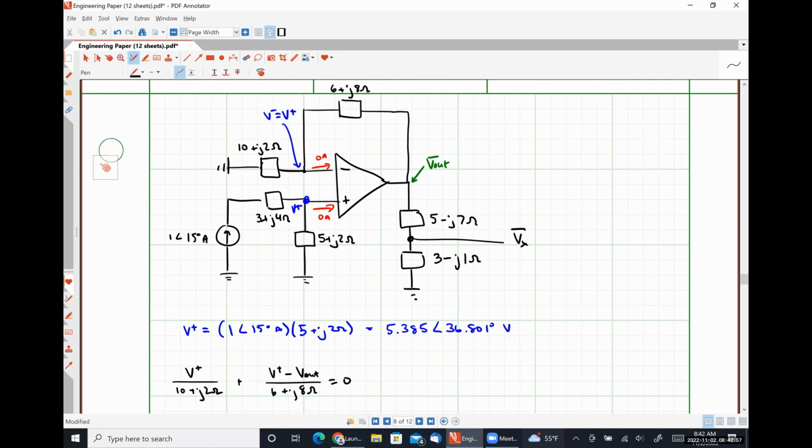If we are doing the 3-step process, another thing that I could do, for those of you that paid attention on the second day that we covered op amps, is once I know what this voltage V plus is, I can effectively treat this as a non-inverting amplifier.